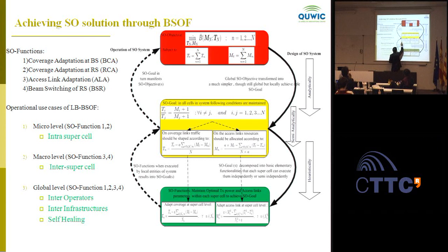And this is for optimal, for minimum blocking, you need to have this much traffic in each cell. Okay, and if TT means this is the total traffic in the system, this is the number of total channels in the system, this is the number of resources in your neighboring cell, and this is the number of resources in your own cell. So for every cell, this condition should be maintained. But again, it's difficult to maintain it.